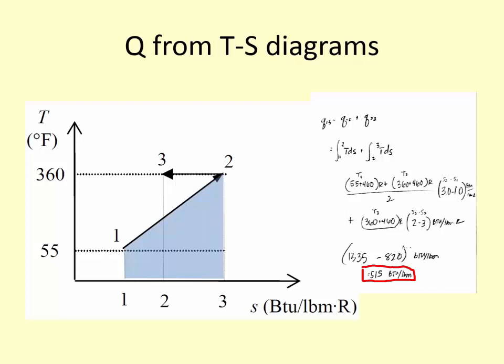We don't know the functional relationship. We don't actually have to calculate this integral, but numerically we can calculate the area under the curve, which is what an integral represents, because it's linear. So we can calculate the area under the curve for those two cases. Important to note that we want this in terms of absolute temperature units, so we would convert to the absolute temperature. And from Fahrenheit, it's easiest to just convert to Rankine.